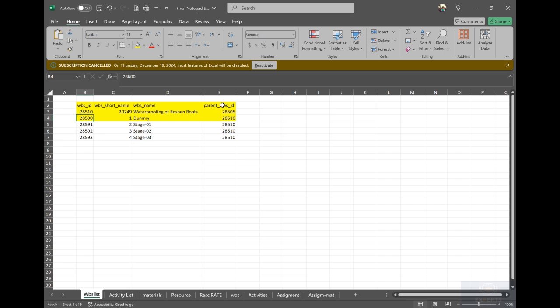And what is the WBS parent? What is the parent WBS for this dummy? 28510, which is here. So we have to follow this. We explained it already in the course, but we have to repeat it again. What I will do, I will insert my WBS which we have here. We have here 3 WBS, but consider that you have 500 WBS or something. Copy paste from your sheet. You have to prepare one sheet including all your breakdown of the WBS. You will take it and copy and paste here.